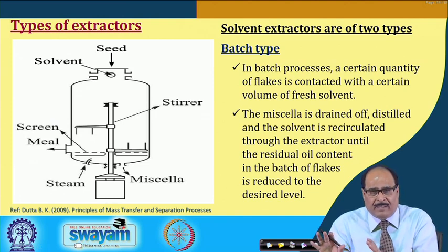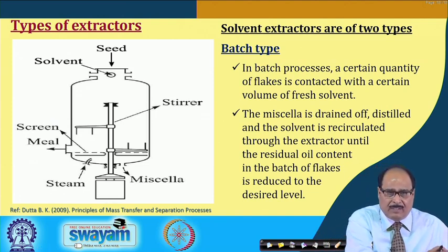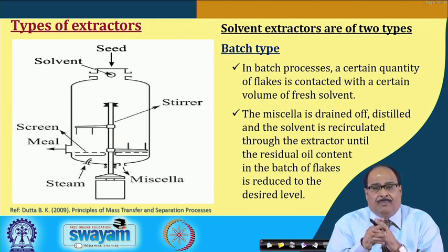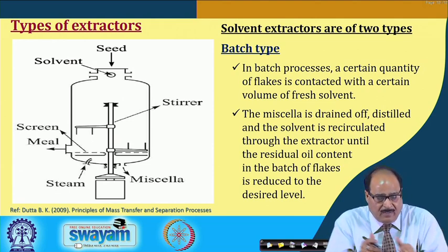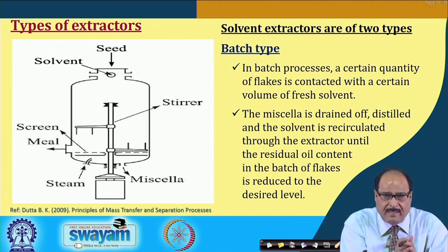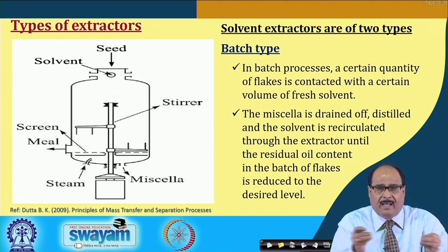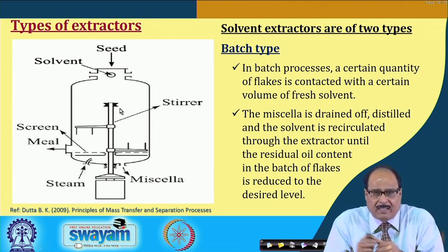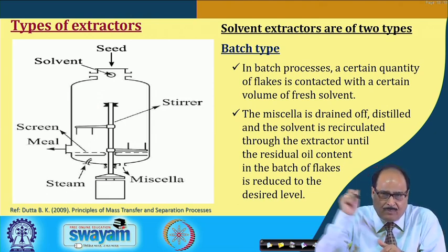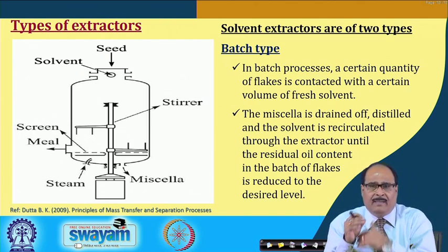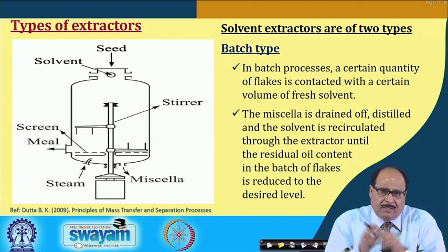So, now let us see: you have seen that the prepared or flaked and porous mass is fed to the solvent extractor, in which conditions of temperature, pressure, etc. are maintained, and there is a direct intimate contact of the prepared mass with the solvent. Solvent flows and penetrates into the mass, the oil dissolves into it, and then it comes out along with the solvent.